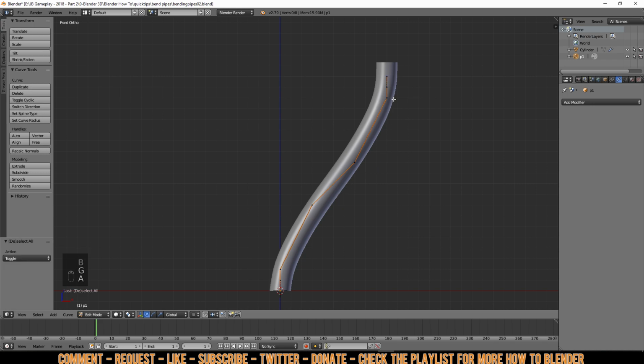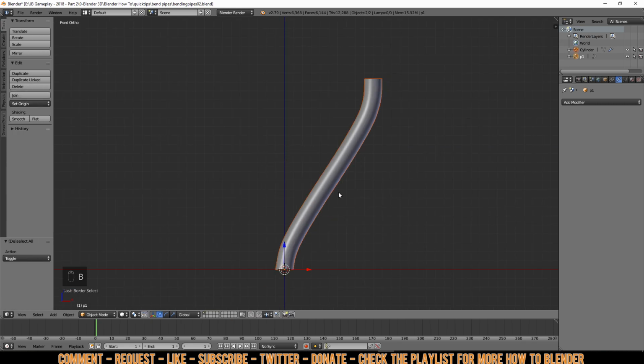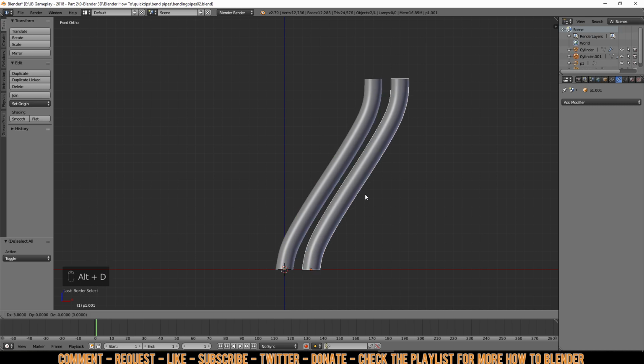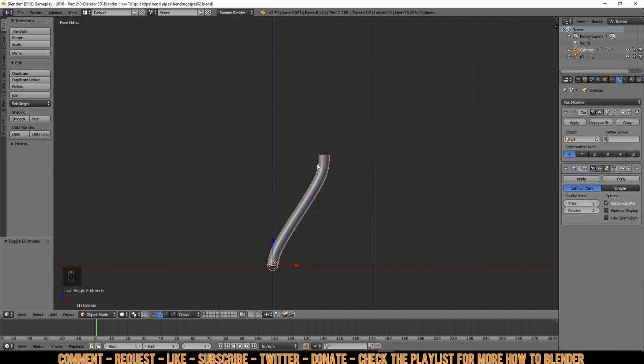And now I'm going to make sure that this line is straight with that line. First things first, let's select both of these, press W, add in another subdivide, and then just start messing around with this. I believe I only have to put that one up and this one down, and now you can see we have a nice straight line. Now if I select both of these and Alt D them and place them near each other, you can see we now have a much nicer gap between, in case you want to make a video card or something like that. But we will have to fix the top first because it's past the line.